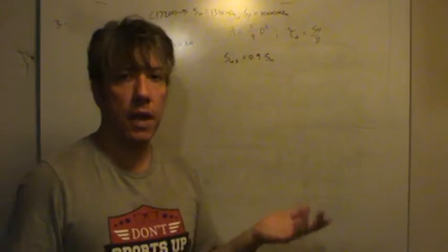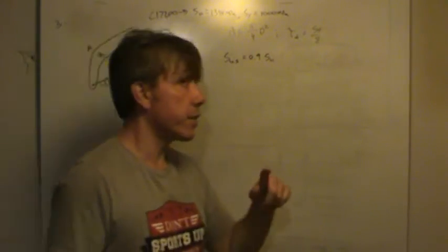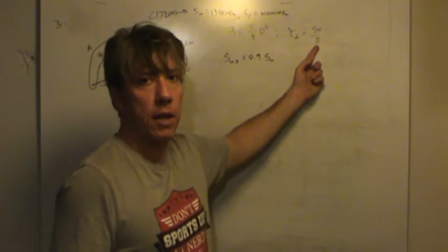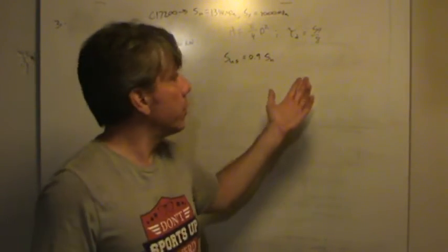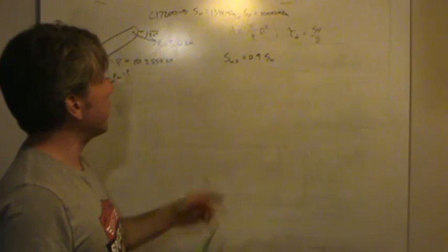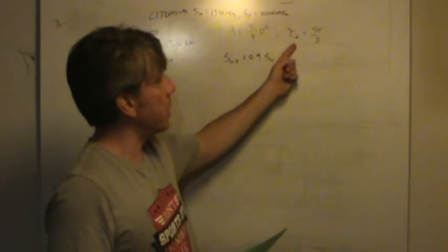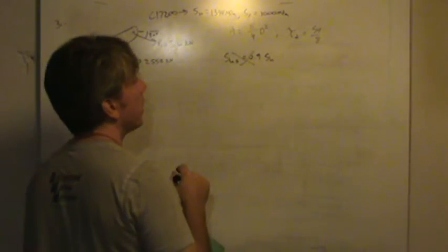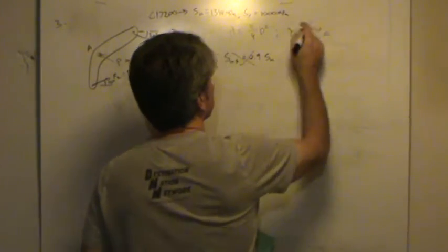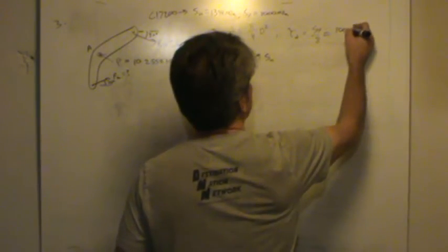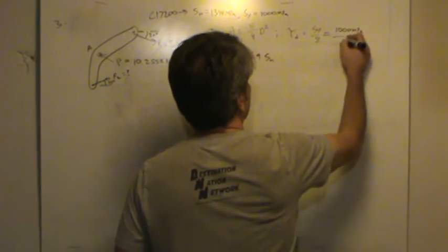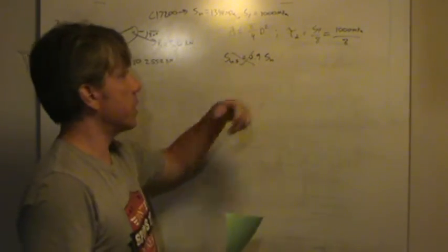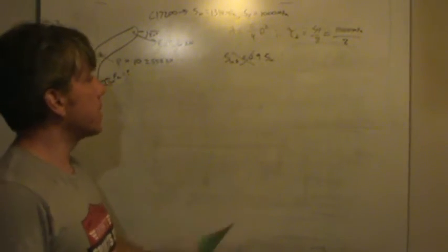Now if I use a design factor that's greater than the one for ductile materials, then I need a number larger than 8. So say 10, I don't know. We could use something. The point is that I'm still going to effectively end up with about the same design stress. So I decided, forget all this, we're close to a ductile material. I will simply use the yield strength over 8 and get about what I would, say, if I used a design factor of 10 with 90% of the ultimate strength. And so that's what I chose to do.